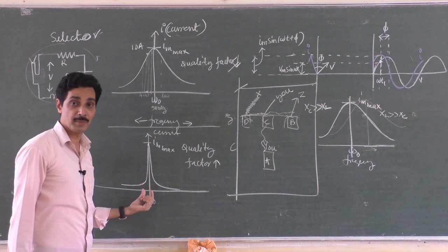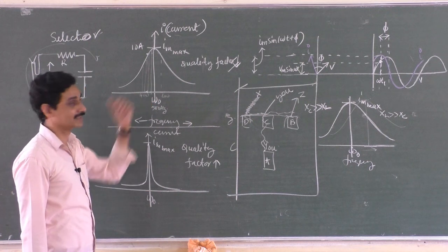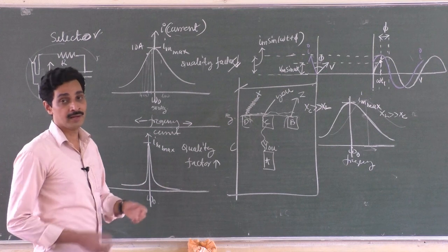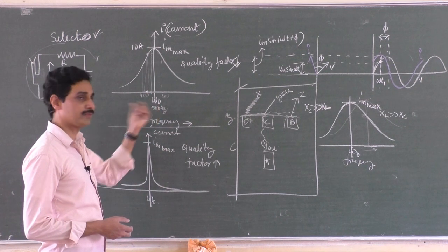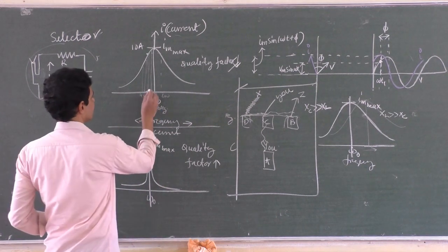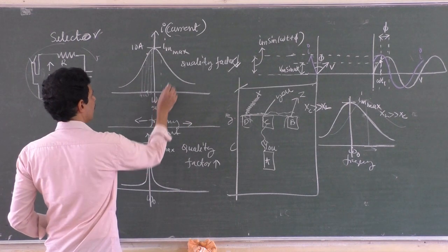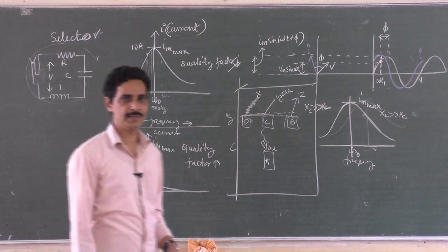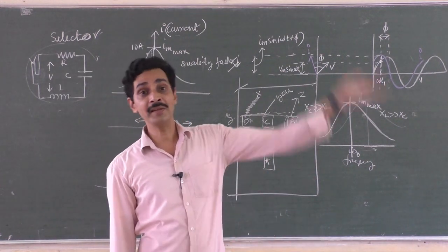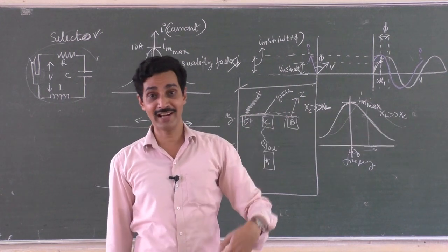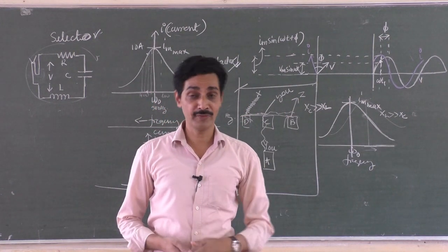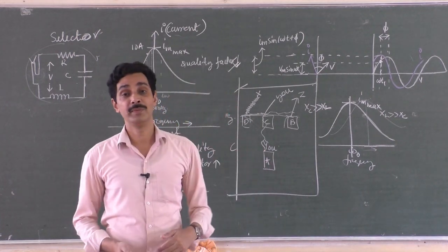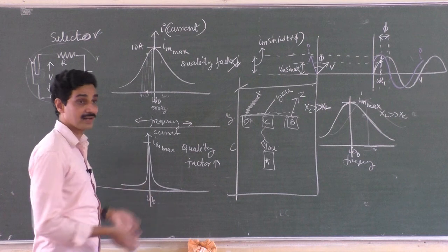And this is also needed in mobile. See, suppose the mobile circuit is like this, what will happen? If my mobile has a resonance circuit like this, it will select 500 Hz. It will select 400 Hz also. It will select even 300 Hz. And from 400 to some 800 Hz, all the frequencies are selected. That means those who have called other mobiles whose resonant frequency is different, those signals will also come to my mobile. Of course, they will be hitting all the mobiles, but my mobile will receive signals of other mobiles also.